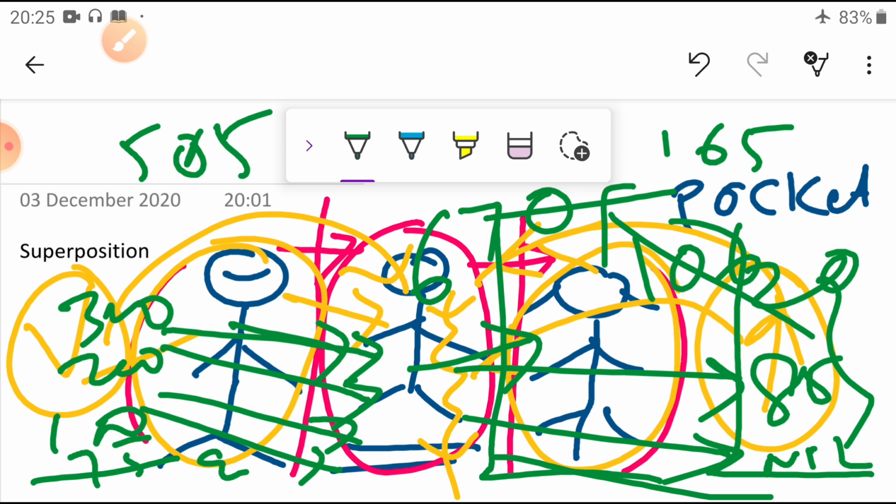Similarly, in our networks also, assume one source at a time, and keep the remaining sources aside. If that source is a voltage source, simply short it with the internal resistance of that source. If there is no internal resistance, the ideal case, then you simply short it. We know that it is not possible to get an ideal voltage source. Every source has its own internal resistance.